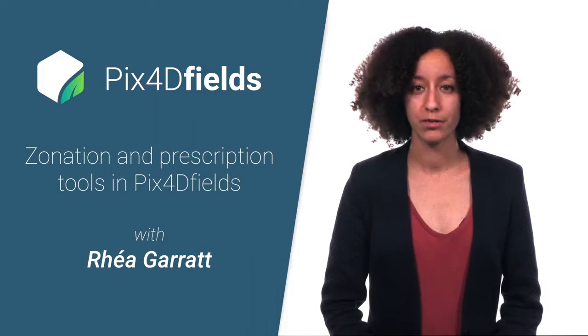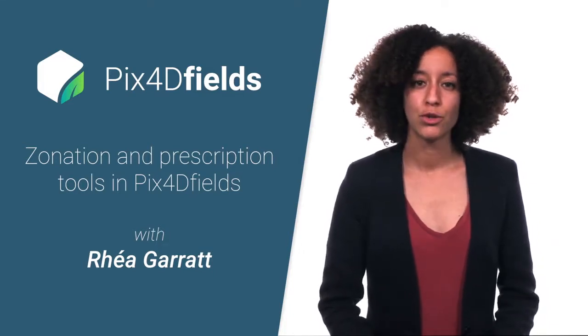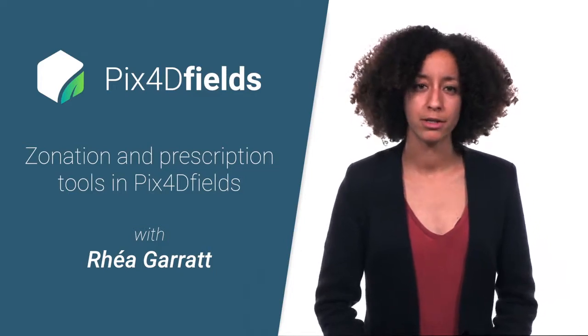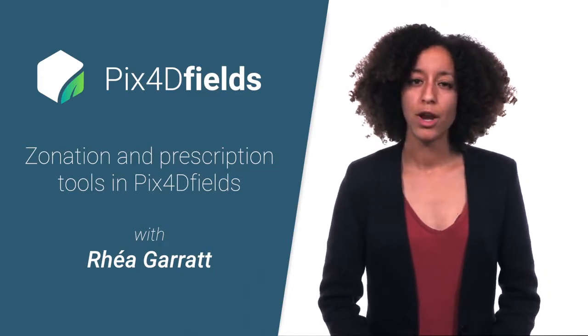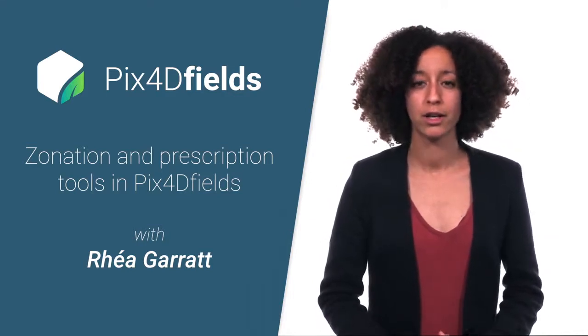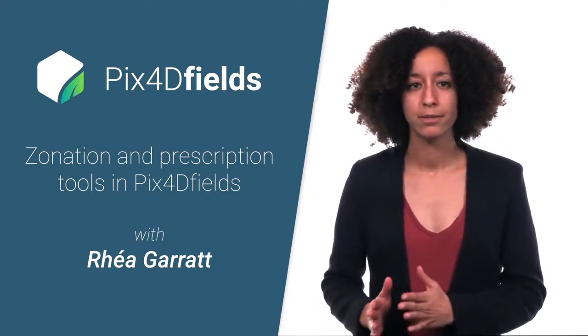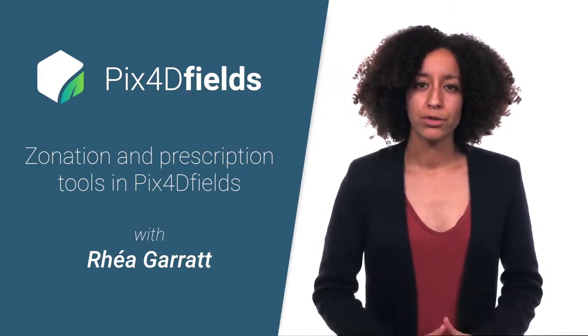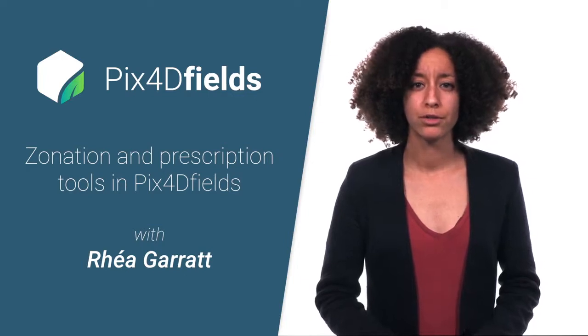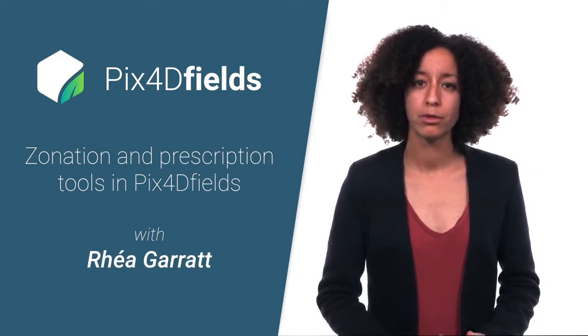We will use the zonation and prescription tools in Pix4Dfields. Zonation layers and prescriptions are products of the vegetation index maps. The zonation tool allows you to divide the values of a vegetation index layer into several classes. Prescriptions are added to a zonation layer and are used by smart tractors and farm machinery for variable rate application.